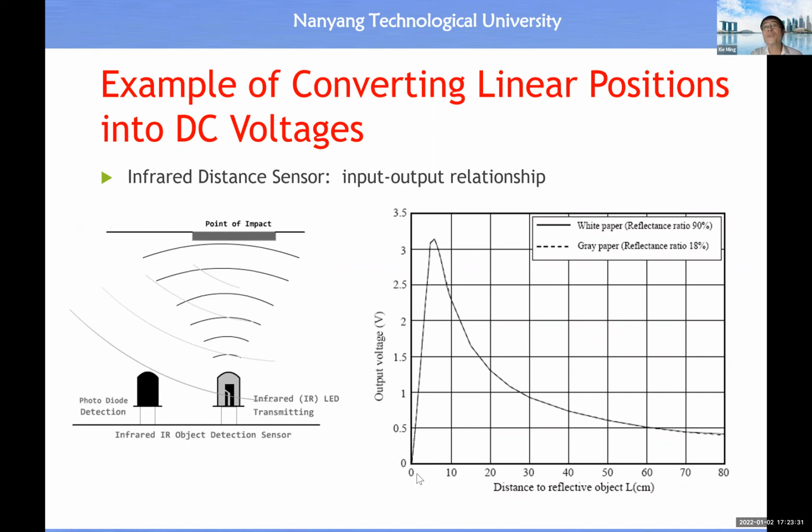Or you can implement a decision rule to know whether the value corresponds to sensing in this short range or in this long range. In this way, you can also detect the presence of an object very close to the sensor. So it's up to you. This is the typical response from an infrared sensor.